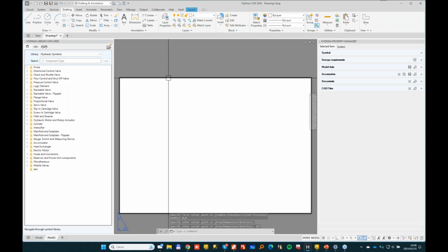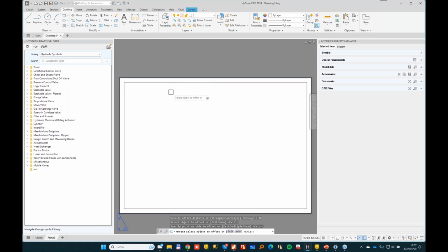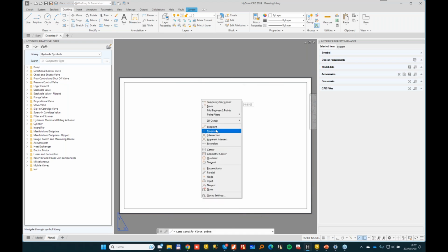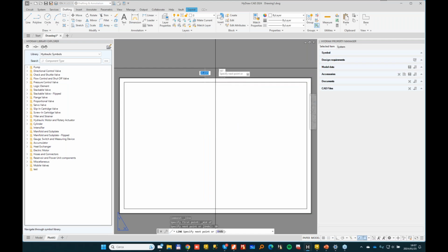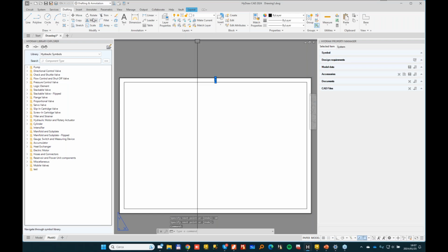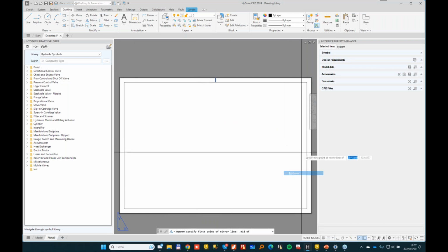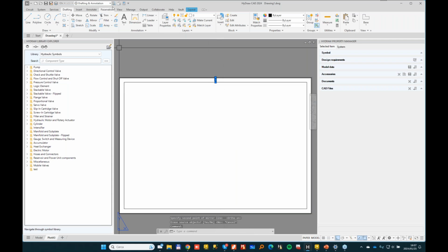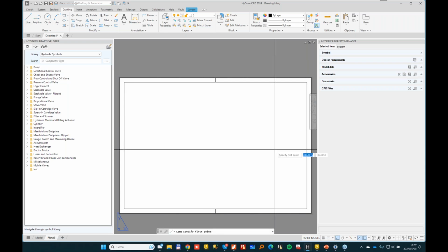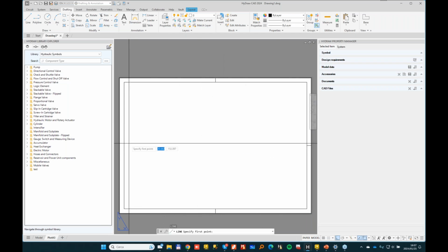I also want another frame. Let me do an offset of 10 millimeters from this rectangle. And then if you want, you can add the midpoint. So 10 millimeters. And we can use the mirror command to mirror entities. Midpoint, F8. Let me do it again. Mirror. Shift right click to select the midpoint. And so on. And also we do here, shift right click, midpoint, 10 millimeters. And also from the other edge, midpoint.